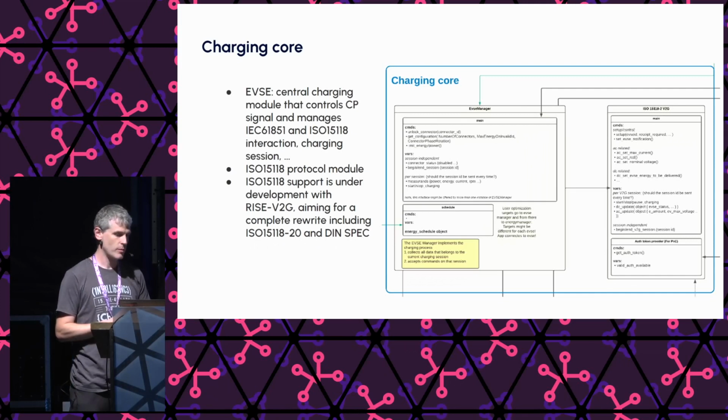So they put an Ethernet link on top of that by using powerline Ethernet over the same wire, which means there's also the so-called high-level communication with ISO 15118 or DIN-spec, which is essentially a protocol based on XML, where you can talk with the car, and it gives you more details such as how many kilowatt hours are required by the car to fulfill its charging target, and how big is the battery, and a lot more information that you can get out of that car while charging.